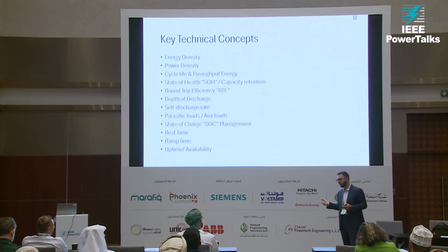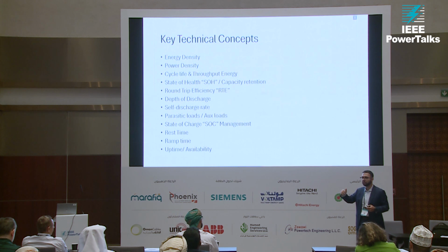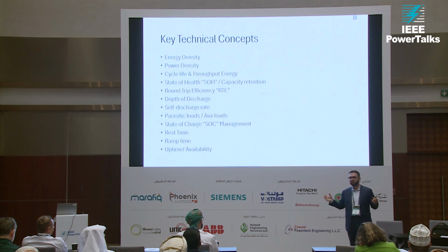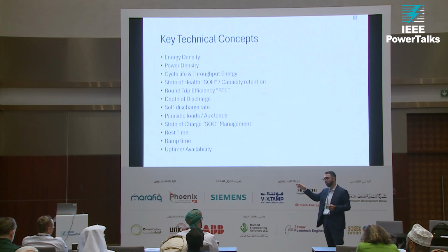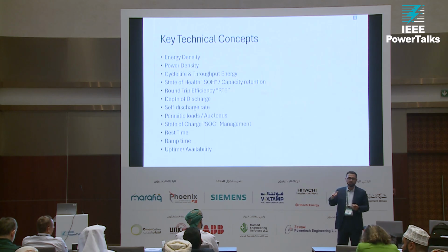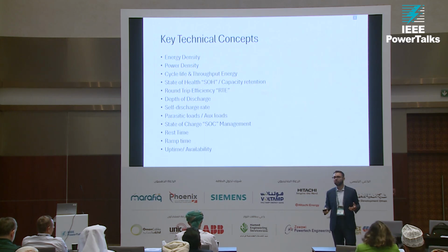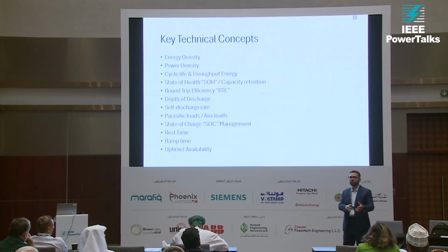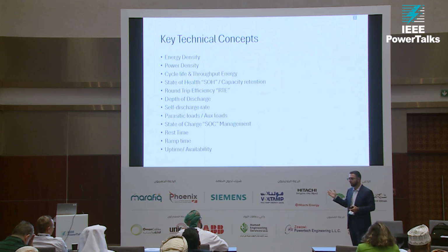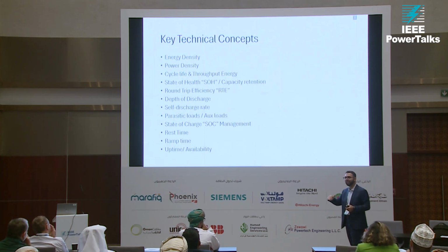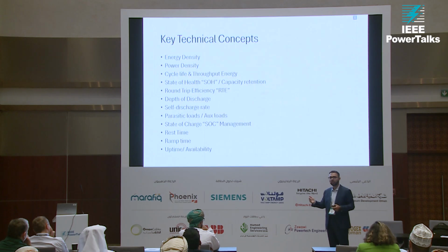With electrochemical energy, with special lithium-ion batteries, what we've seen is you can go up to 99% because there are a massive amount of cells that can all be synced together to get a uniform 100% across all cells. We'll talk about this later in the presentation. Similarly, when you discharge, you can't go all the way to 0 because some cells will go to 0, but not the entire system. So when you average the entire system, it's not going to go to 0. With electrochemical, we've seen that being 99.1%, so you're only losing about 1% in your depth of discharge, which is great.